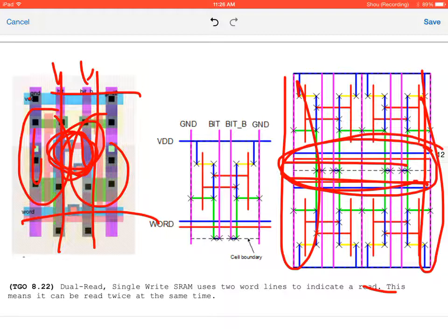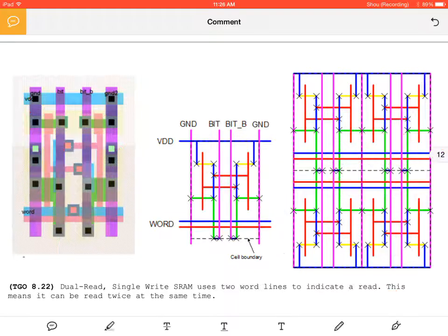SRAM cells. Now, common mistake, people are trying to build it up and they don't size it properly, so they'll actually have this separate over here. So a lot of designers will waste a lot of area by not considering that, hey, I can use this layout overlap and use that tool to test it before I merge everything. Here now you've reduced a lot of area. It still works exactly the same. And especially when you're trying to consider how to make it as small as possible, these kinds of techniques, especially for memory, become extremely helpful.